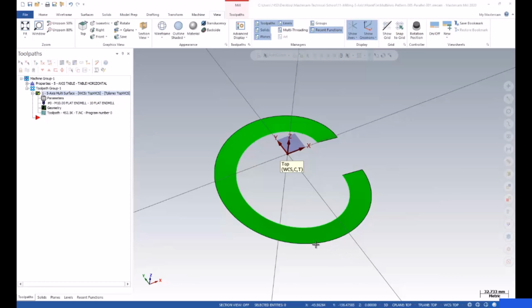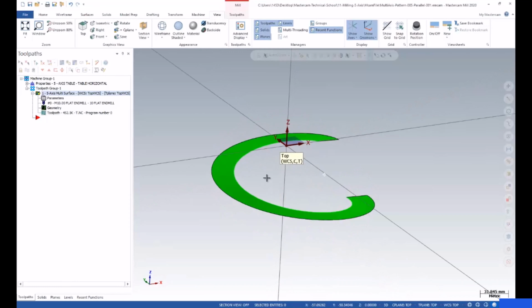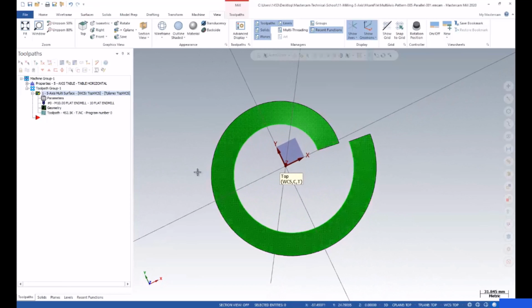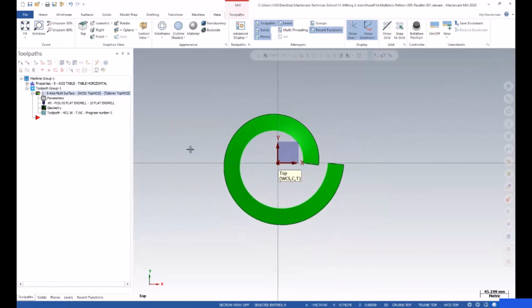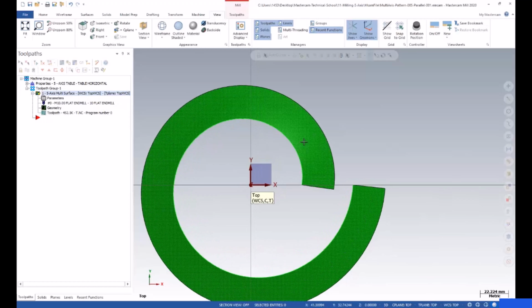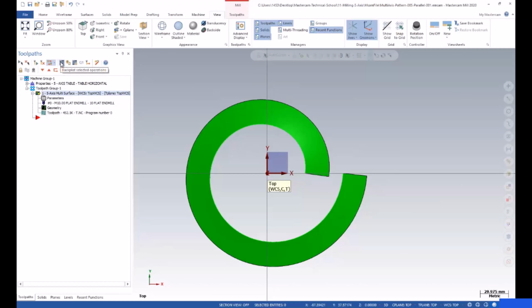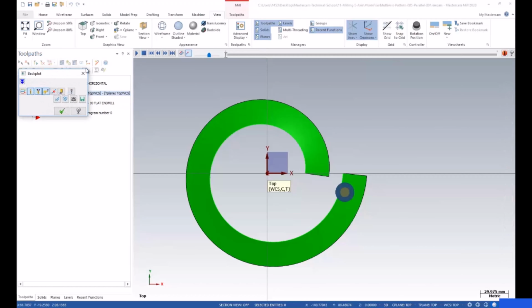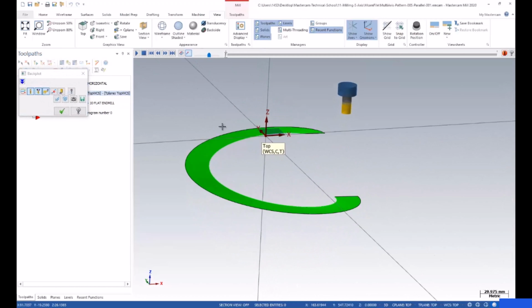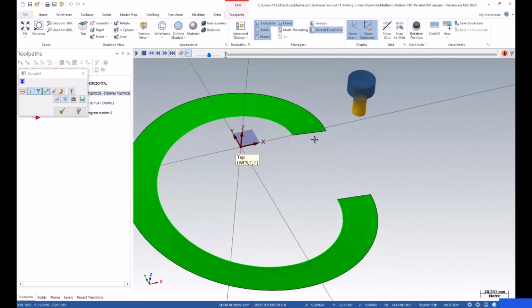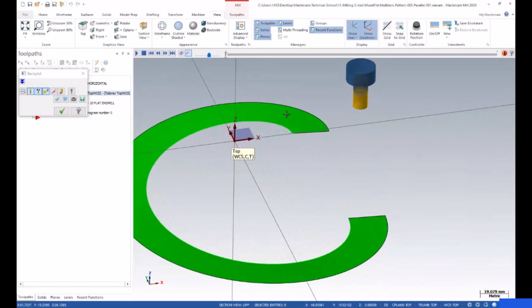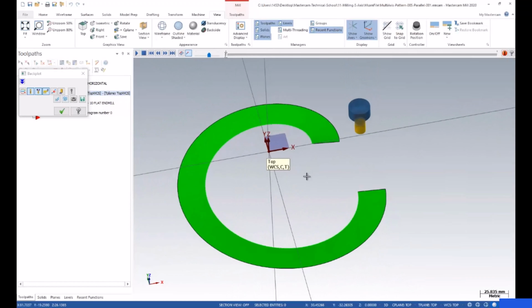Okay, in that lecture we can talk about MasterCAM 5 axis again. So you can see a simple example designed by me. So I can easily explain to you how we can use the 5 axis process in MasterCAM. So okay, let's show, with the backplot simulation, I'm gonna click on the backplot simulation. As you can see, I used a flat tool. So it means that of course for that kind of surface I need to use 5 axis.